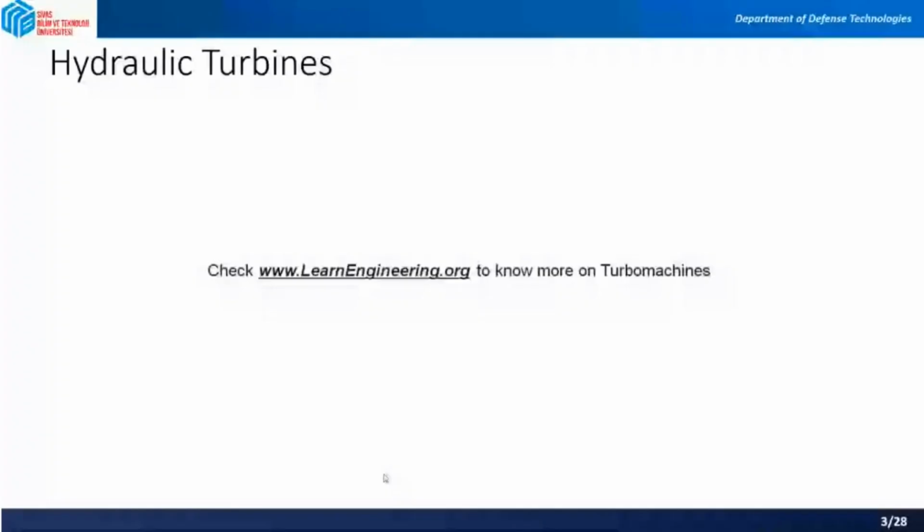And as I said, this figure shows the axial flow turbine, only the rotor blades. So the stator or nozzle guide vanes are not there. In the case of a reaction turbine, we said that the pressure drop of expansion takes place in the stator as well as in the rotor blades. So the blade passage area has to vary continuously to allow for the continued expansion of the gas stream.